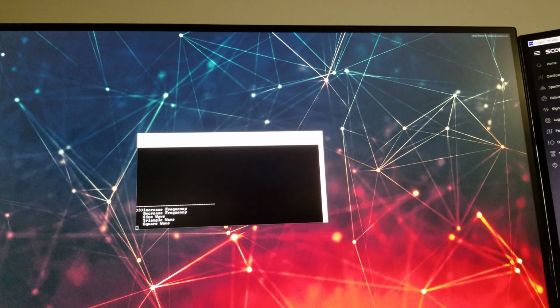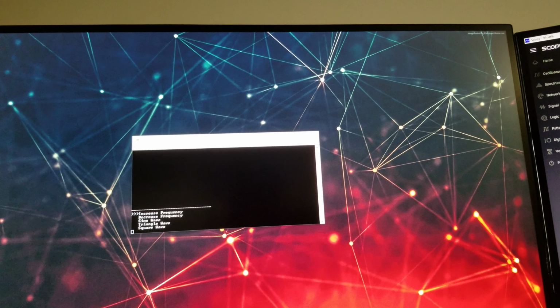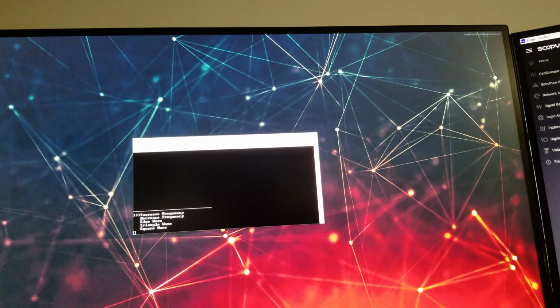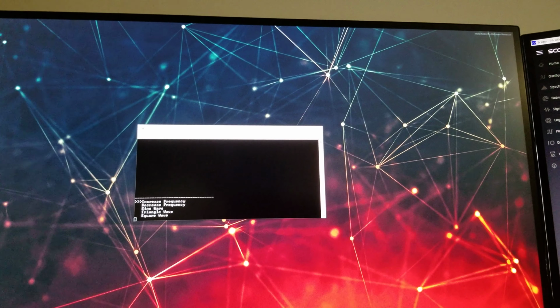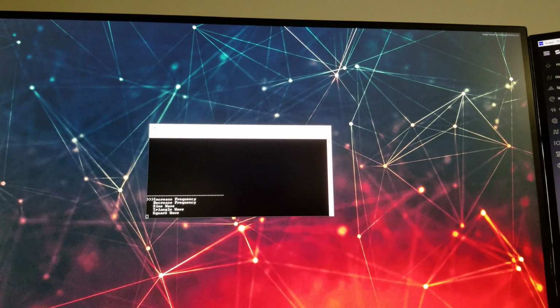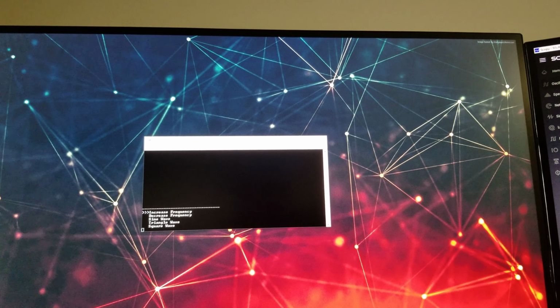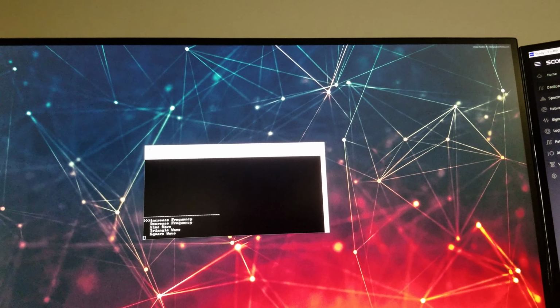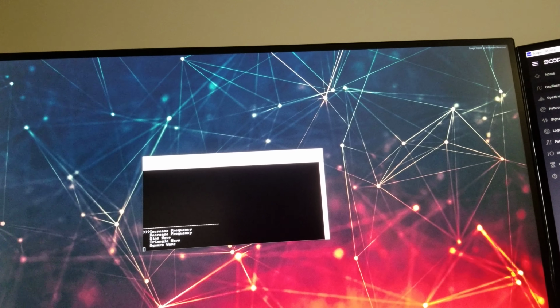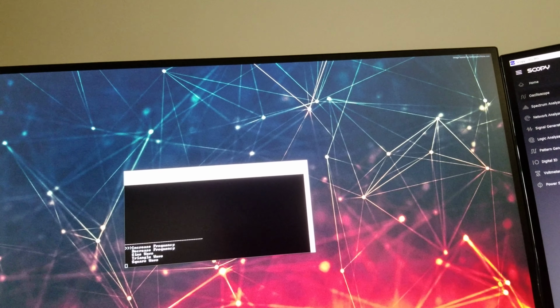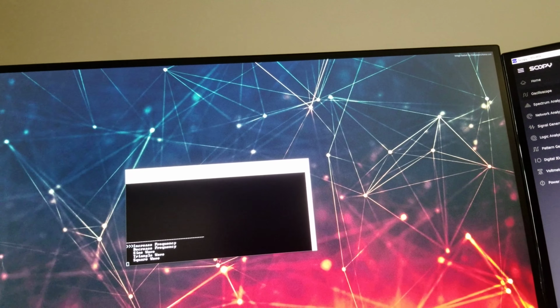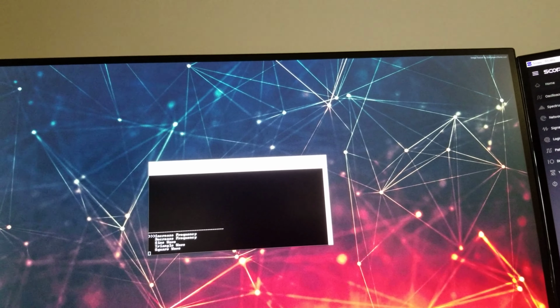I had the APB1 clock configured to 64 megahertz. So nominally, the fastest we can go is 64 megahertz with a prescaler of 0, and I've set it up so that the PWM has 255 pulses per period. So that comes out to 64 megahertz divided by 256.